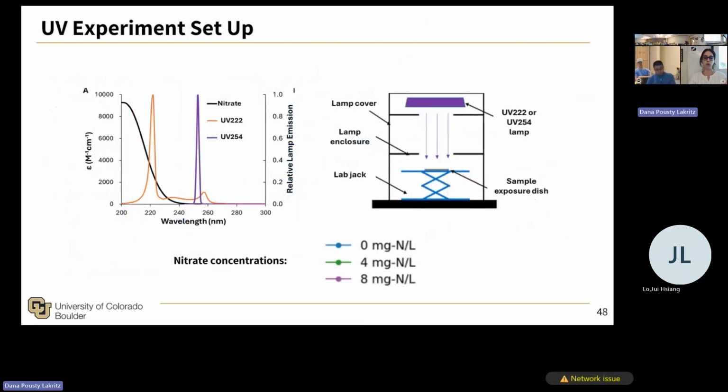So we compared 222 nanometer and 254 nanometer, and I took water with MS2. MS2 is a virus, and it's really very hard to disinfect. It mimics cryptosporidium in the water. Cryptosporidium was very hard to disinfect, and chlorine was not able to disinfect it as well. During, I think, the 80s, a very talented researcher, Professor Jim Bolton, who unfortunately passed away, one of the founders of this UV technology, found that UV can disinfect this cryptosporidium, and then everyone wanted to try UV.